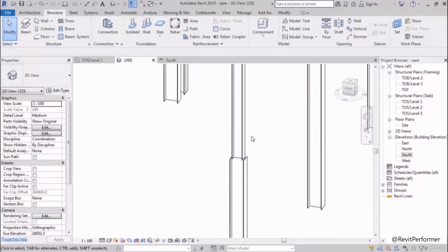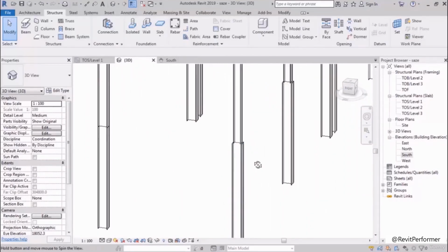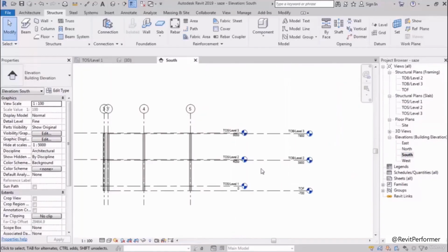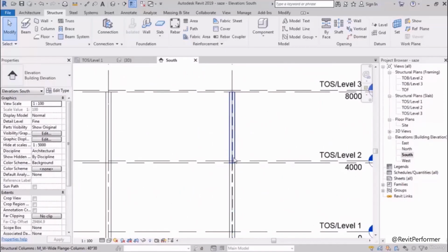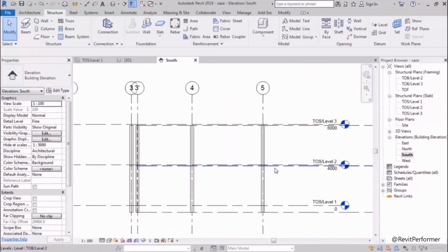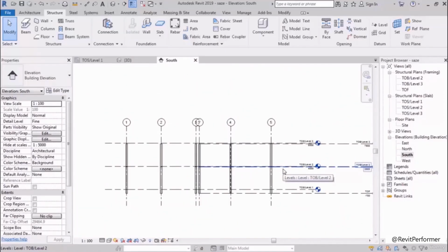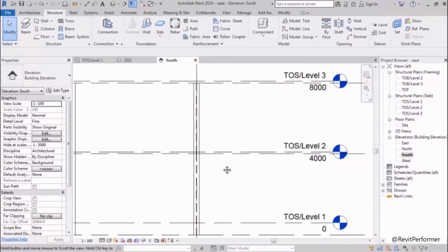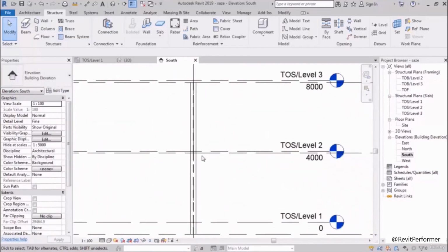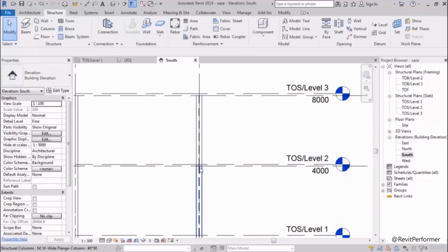Now, a very technical point. The place where the columns are cut, where there is the section change of the columns, is called a splice, or we can say SP, splice. In the view, here is called the splice. Now, the splice never happens at the level of the floor, because here we have the loading.